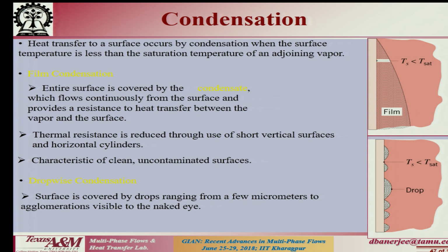Okay. So, as a result, these droplets tend to form almost spherical structures rather than a film. In the case of film condensation, because the attraction of the solid for the fluid is much higher, it spreads out, because the attraction between the fluid molecules is less than the attraction from the solid surface to the fluid molecules, right. So, once you have droplet condensation, you have very discrete droplets that form on the surface.